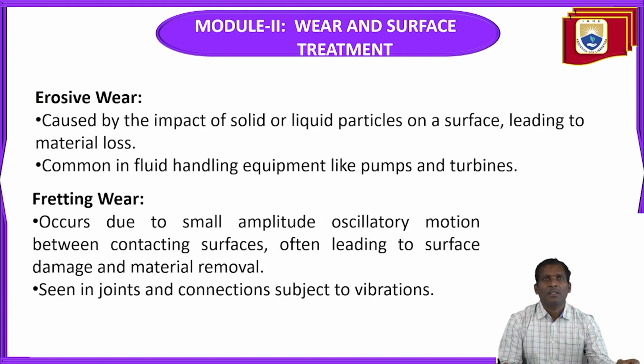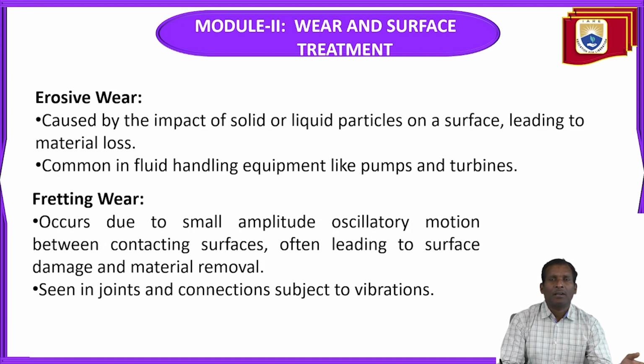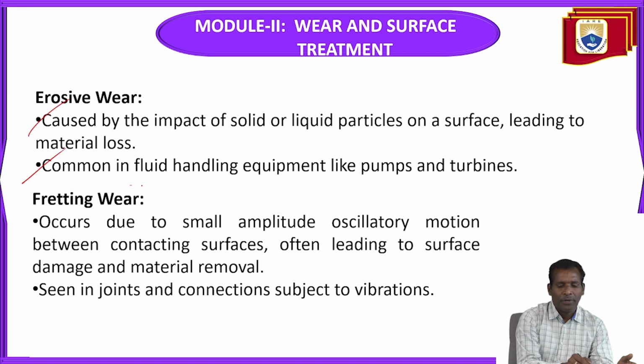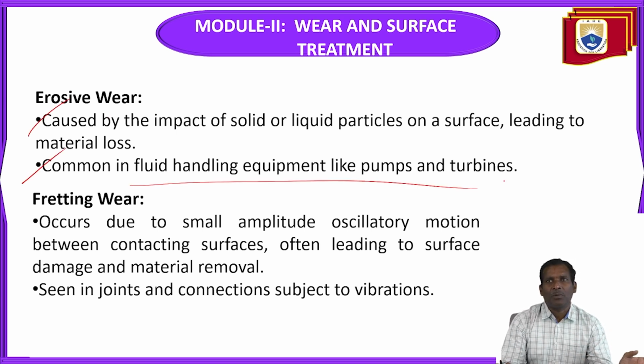Next, erosive wear caused by the impact of solid or liquid particles on a surface, leading to material loss. It is common in fluid handling equipment like pumps and turbines. Fretting wear occurs due to small amplitude oscillatory motion between contacting surfaces, often leading to surface damage and material removal.